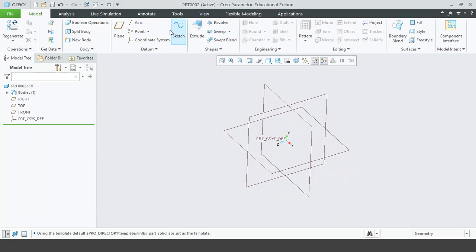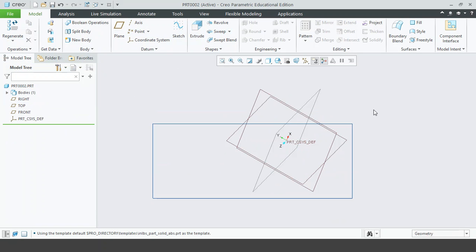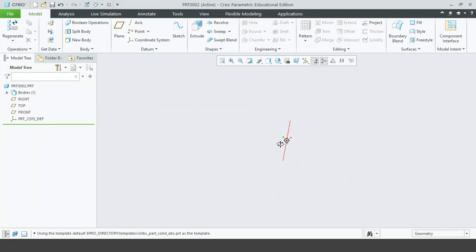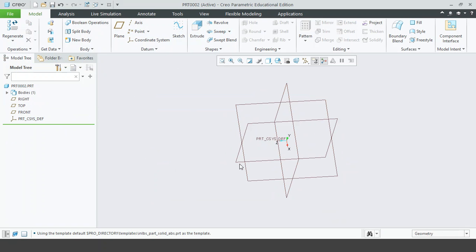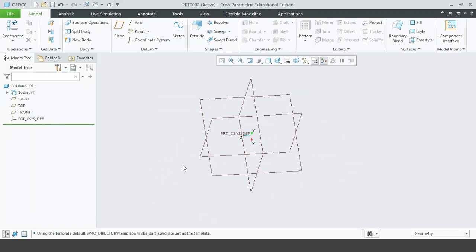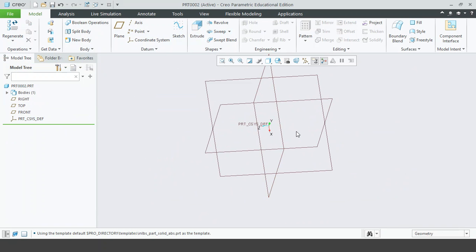And over here you have all the options that we could do, including sketching and extruding, which we will use as well. So for now, I'm going to teach you the basic controls. If you have a mouse, then you can hold down the left mouse button and drag it to select anything you want on the screen. Here you can see what you select and drag over will turn green. If you hold down the middle mouse button or the scroll wheel, then you can drag it and it'll be able to rotate around the screen. If you hold down the middle mouse button or scroll wheel again, while also holding down shift, you'll be able to pan around the screen a little. And of course, if you use the scroll wheel, you can scroll in or out at the exact point your mouse is hovering over.